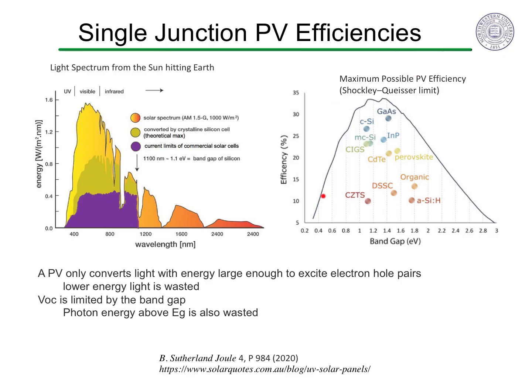At small band gaps, all the photons are converted, but the voltage they produce, limited by the band gap, is small, so the power output is low. At high band gaps, only the high energy photons are converted, while most of the photons with lower energy are wasted. Thus, the efficiency of a photovoltaic tends to peak around 1 to 1.5 electron volts, where silicon and gallium arsenide have their band gaps. Commercial silicon and gallium arsenide photocells now have efficiencies above 25%, close to the theoretical maximum.